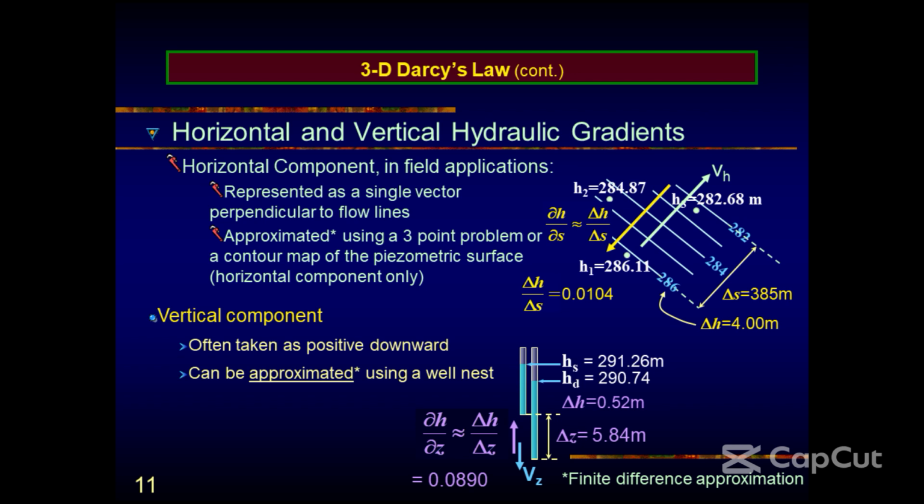So that will now take us into the knowledge of the flow in the unsaturated zone. And all these aspects of capillary fringe and water table will now come into play very well. But like I mentioned, we will not go deep into that, but just so you know that it plays an important role. The phreatic surface is usually imaginary because it is the surface where the pressure head, the atmospheric pressure, is 0. And then you have the capillary fringe above it.